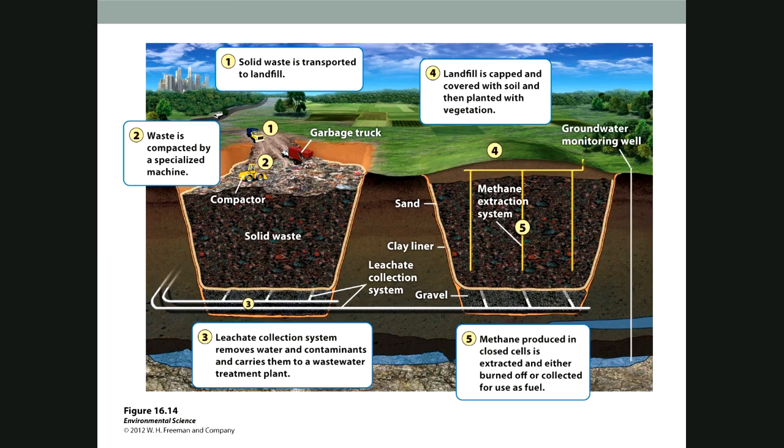This is just a cross-section of what a landfill looks like, so you can see some of the engineering that goes into it. Landfills often have these clay liners to protect the waste from the surrounding environment. They often have leachate collecting systems at the very bottom of the landfill. So once that rain falls onto the waste and it picks up all of the toxins as it travels down through the landfill, that toxic water, that leachate, is then collected by this sewage system where it can then go and be treated.